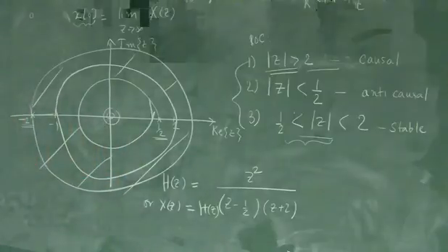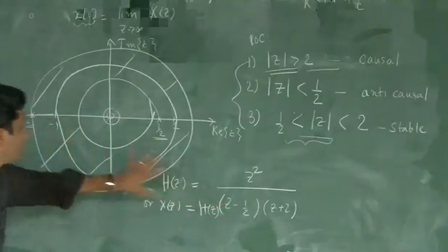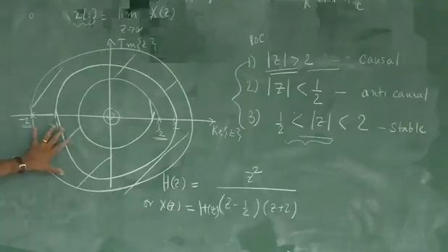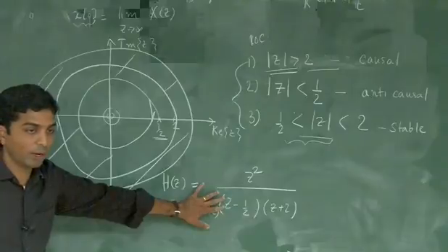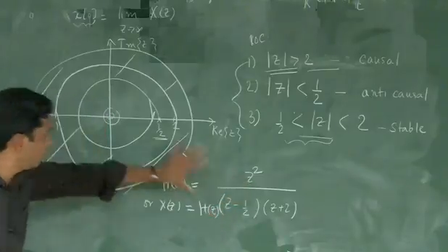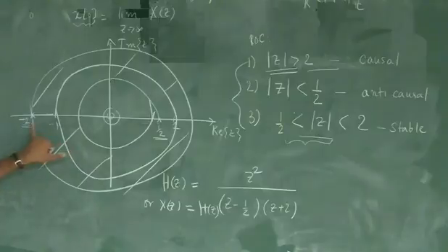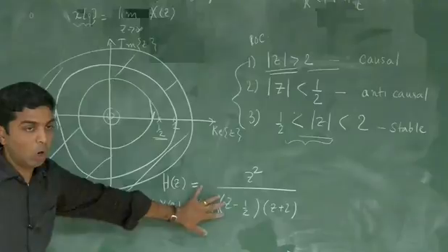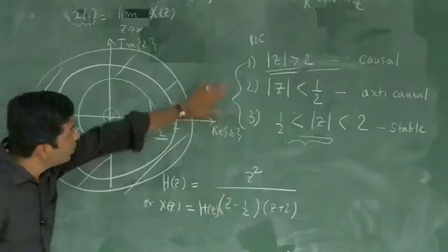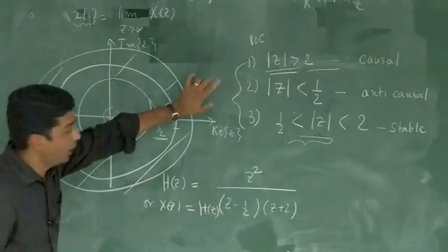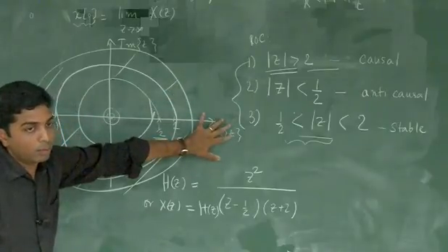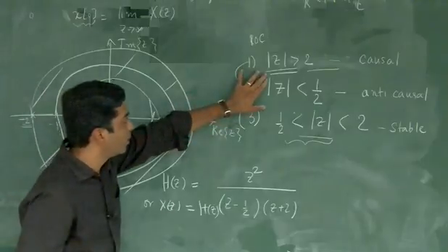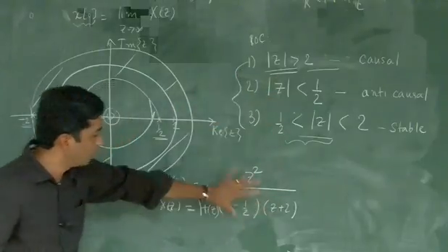For example, right? So if I were to specify something like this, would the poles and zeros that I have specified here satisfy this H(z) or X(z), right? So I'm not giving you this explicitly, I'm just giving you the location of the poles and the locations of the zeros, okay? If I were to have a system like this or a signal whose Z transform is like this, I haven't completed that yet because I have to specify the ROC, right? So the moment I specify my ROC, it's going to become one of these possibilities, right?